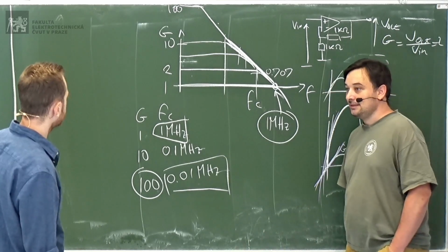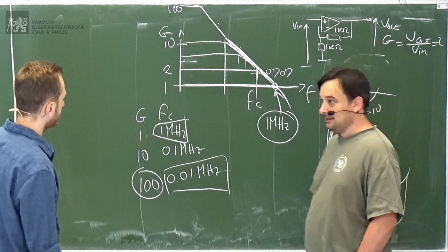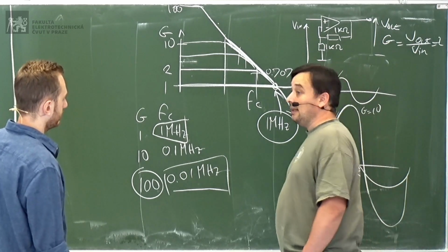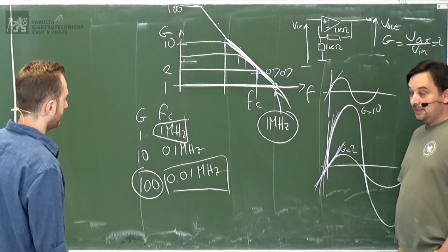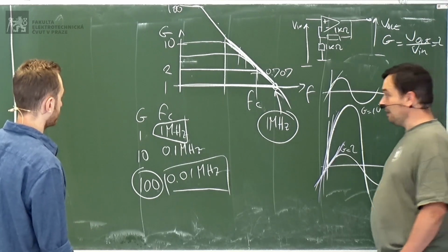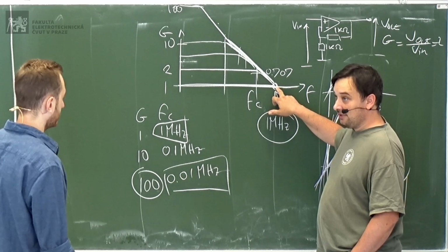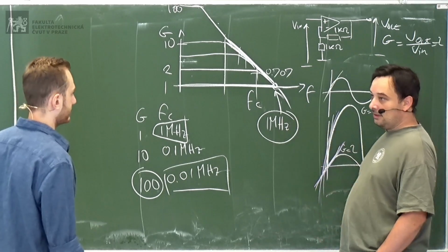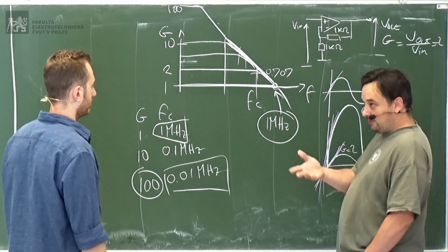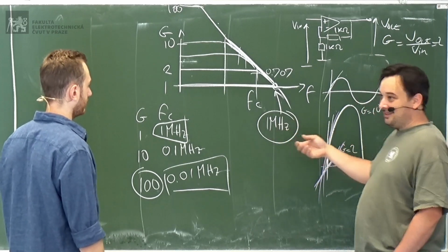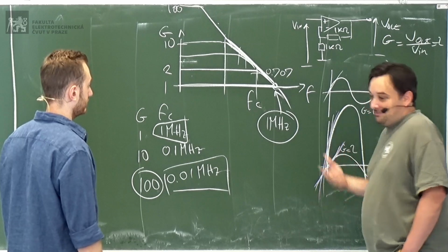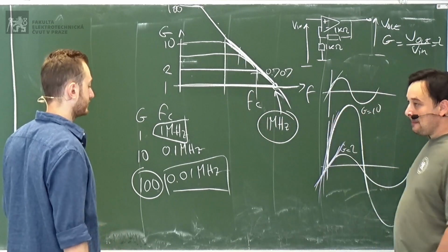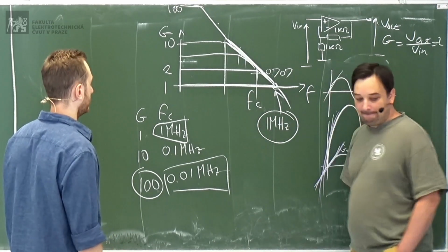I had 100 megahertz frequency response on this op amp I used for my thesis, and the gain is 21 in a differential mode. I have to check the data sheet, but the unity gain bandwidth is 100 megahertz, I think. Wow, that's fast, right? Well, it wasn't a cheap amp. The OP07, the one that you use in the laboratory, has 0.6 megahertz. Okay, so that's like nothing. It depends. If you want to amplify static signals, it's fine. Yeah, this is to measure currents in a motor.